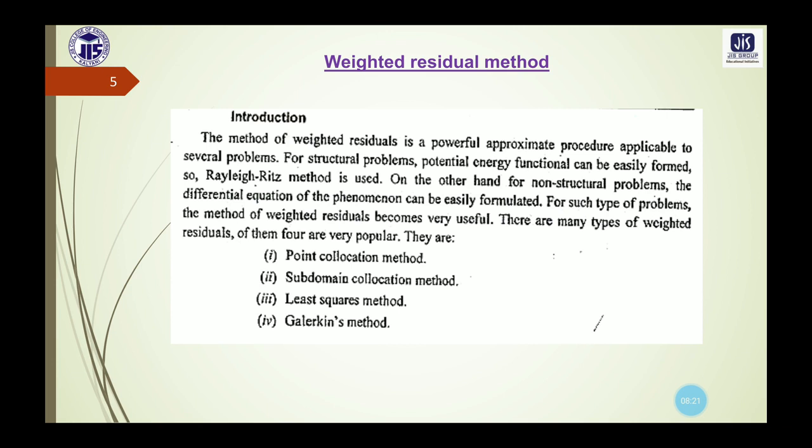There are actually 7 different steps where we have first identified the auxiliary function based on the beam or bar. After that we have found the total potential energy based on the strain energy and work done. Then we have found the Rayleigh-Ritz parameter, and lastly we have found the maximum deflection and bending moment. So these are the 7 different steps of the Rayleigh-Ritz method, and based on those we have solved some numericals.